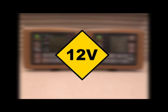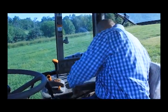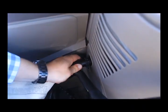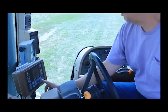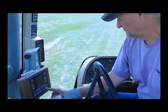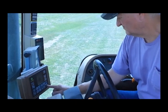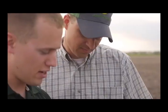Both monitors must have a clean 12 volts of power at all times. If input voltage drops below 10 volts, monitor performance will be affected. To obtain a 12 volt power source, locate your tractor's cab power outlet. Ensure that your tractor power outlet can handle the load required by this monitor. Fuse, relay, and wire size for the outlet must be adequate to handle the load. If you are unsure if your power outlet can handle the monitor load during operation, talk to your John Deere dealer about ways to solve this.